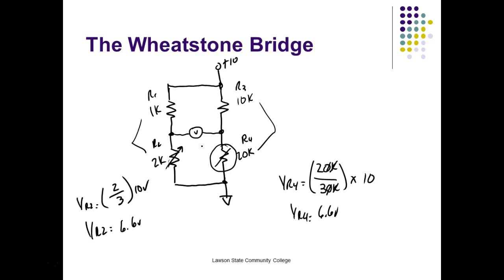You understand? So when we get into sensors that vary their resistance with temperature, you're going to see Wheatstone bridges all over the place. Because it gives us the ability to set a reference. And once I set a reference, then that voltage means something, right? You understand? So this is the power of the Wheatstone bridge. I think back in DC, all you look and see is when it's balanced and when it's unbalanced. But this is what we use them for, right here. This is it. And we've got a lot of devices that change their resistance with what they measure.